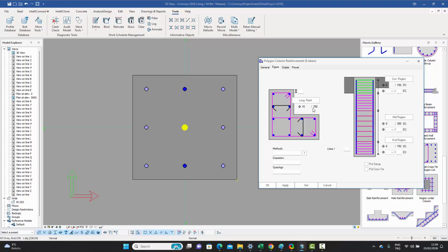Now this 250 was the guideline, but obviously with the column of size 500, if you have your clear cover as well, this is the clear cover from the sides. So let's say that's 50, so that you've got about 400 or something, whatever millimeters left roughly. So 250, if it's exact, they don't fit.